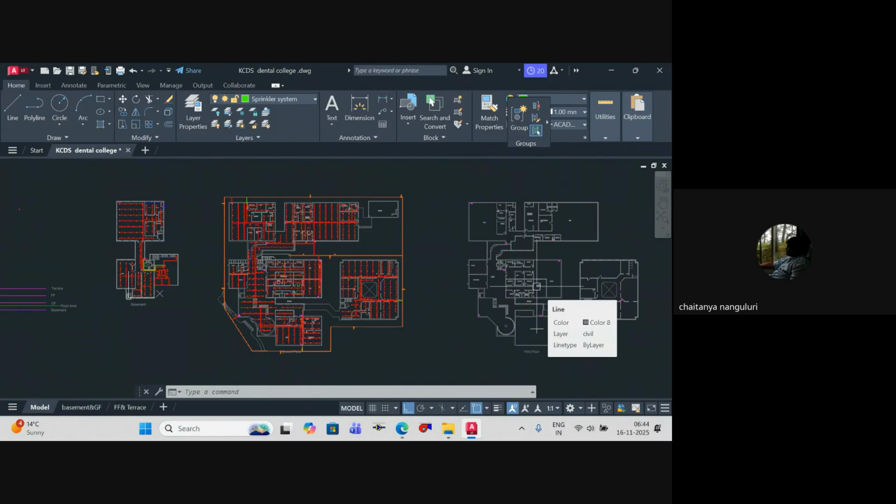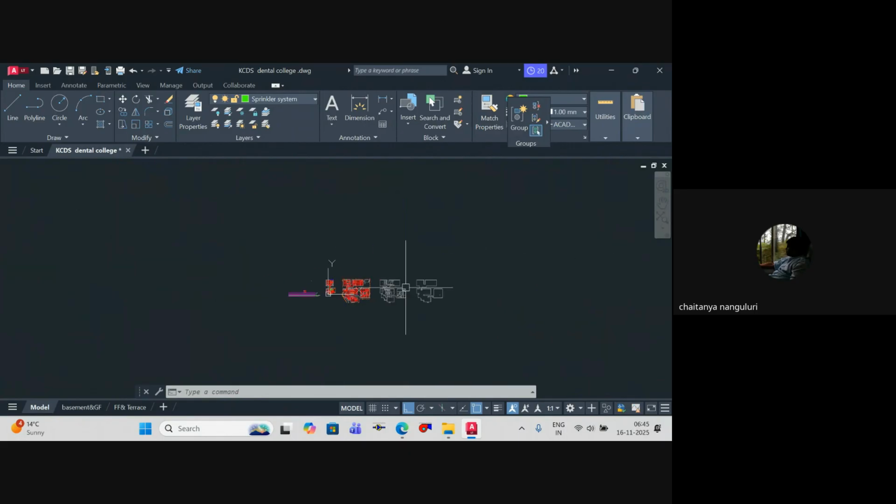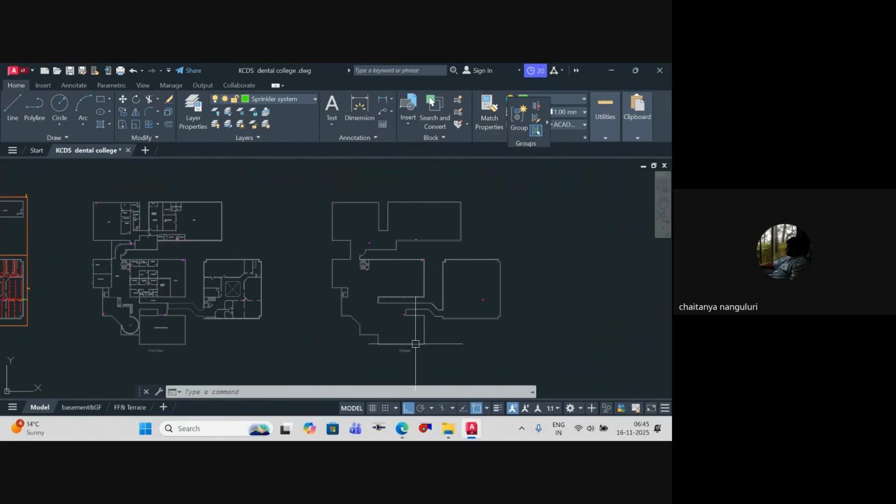Okay, so from the external ring, we are connecting to the hydrant system and the sprinkler system separately. The hydrant system will have an NRV, whereas the sprinkler system will have an alarm valve at the start with an isolation valve, obviously. Clear? And from the terrace, we have to loop all the internal hydrant systems into a single one, and then we have to connect, because everywhere we have got NRV. So we have to connect all these things to a common tank system.